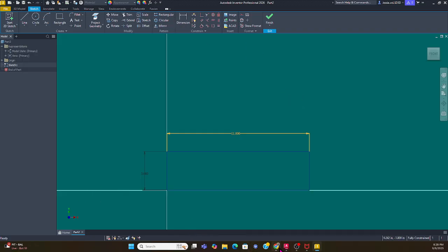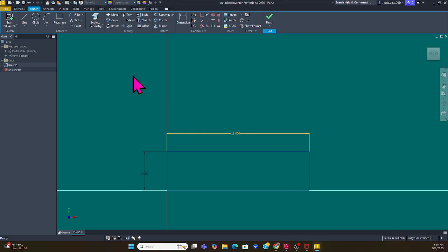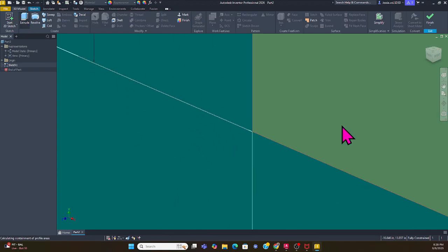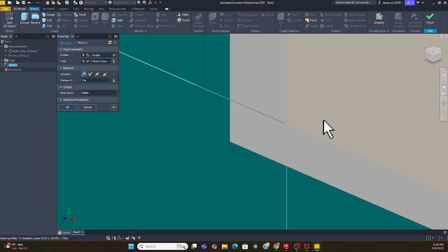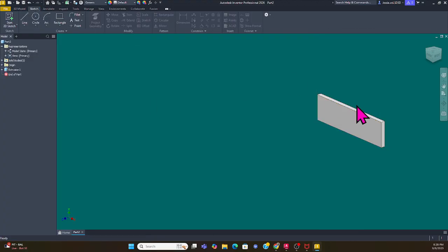As we mentioned, the fold, when we fold the wall up, is 1/2. So we're gonna put that information in as well by going to 3D model, extrude. We're gonna extrude these things. I'm gonna extrude it to the back, and that would be the same as down, and I'll show you later. We're gonna do 1/2, which is 0.5, but we can put in 1/2, and it will pick it up as a fraction.